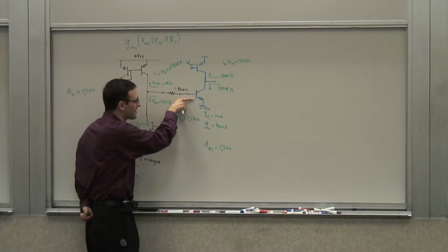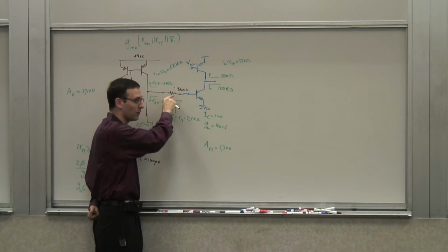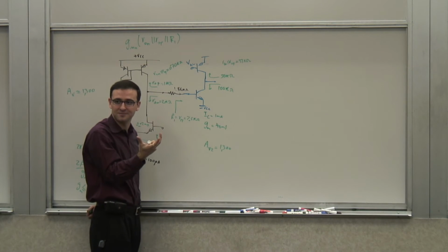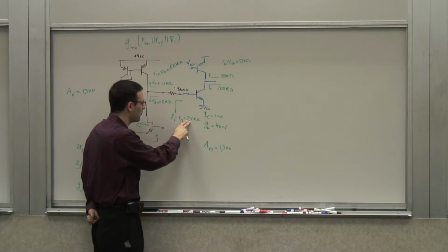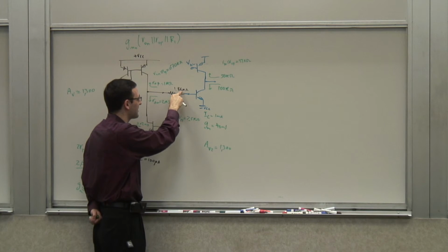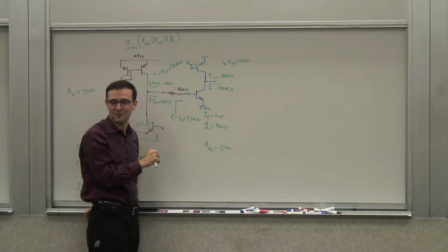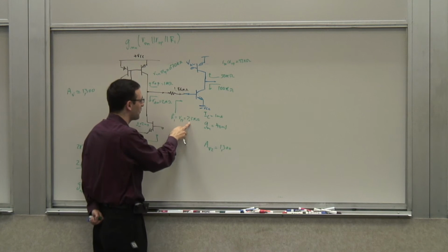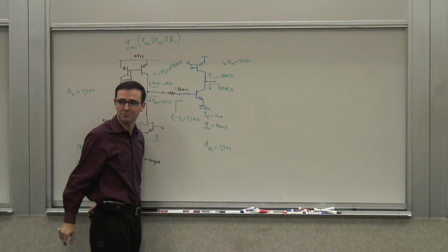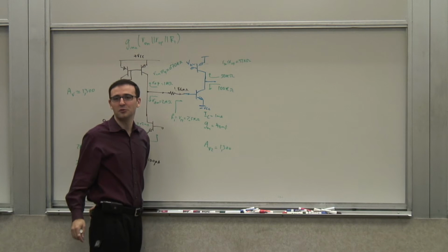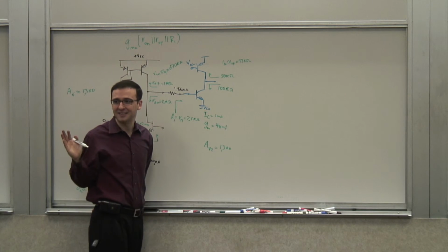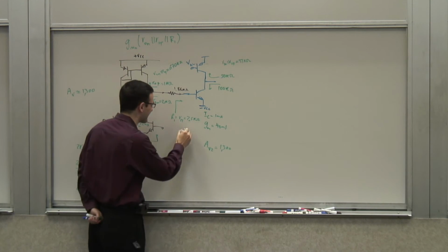Well, you know this impedance, and you know this impedance, so it's a voltage divider, right? This is a resistive divider. What is the divider ratio? It's 2.5 kilo ohm divided by 1.86 mega ohm plus 2.5 kilo ohm, which is practically 2.5 kilo ohm divided by 1.8 mega ohm. So right there, you lose about a factor of 800 in gain. So it has a gain of 1 over 800 approximately.